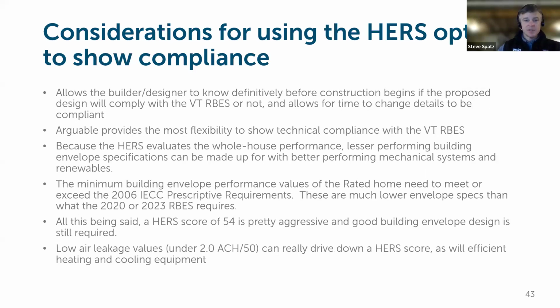So, considerations around using this option versus REScheck or prescriptive compliance. I think it allows the most flexibility to show compliance with the code, because you can balance out a really good mechanical system with maybe some components of the building envelope that are not as good as you'd want them to be, but the design kind of complicates the getting to a higher performing shell in certain areas.